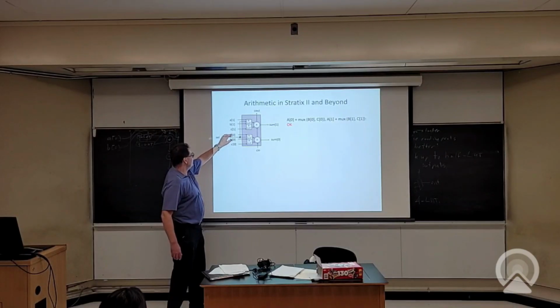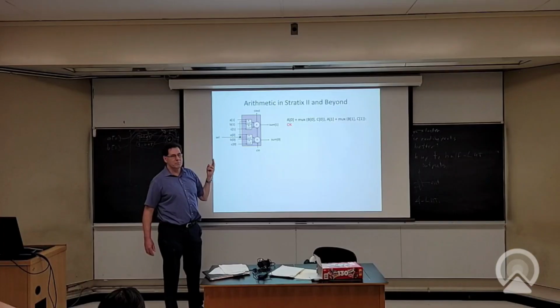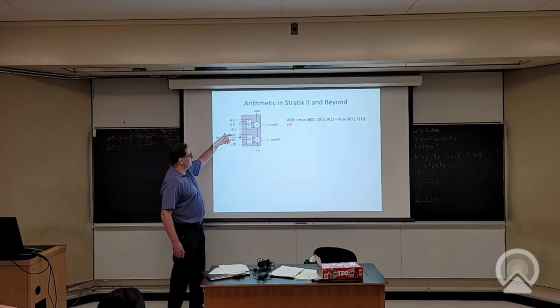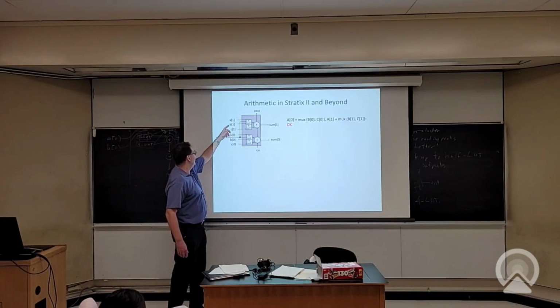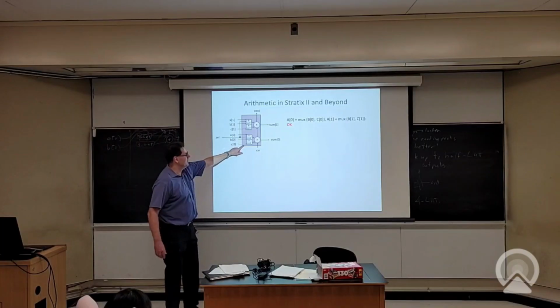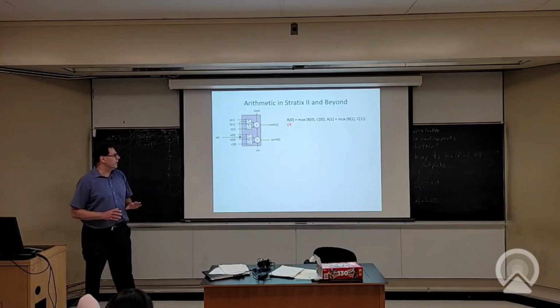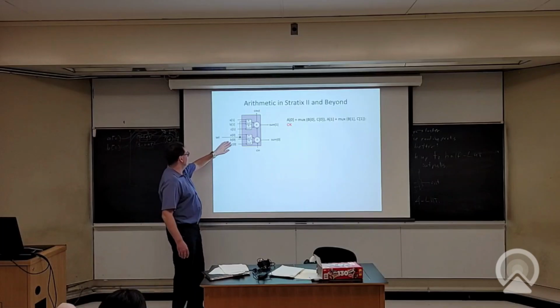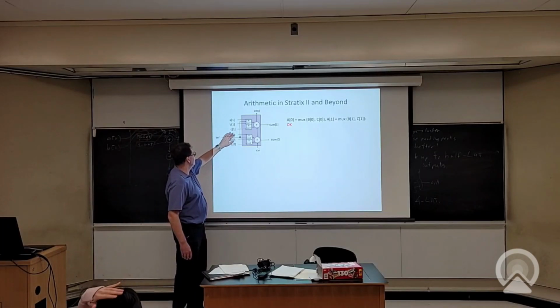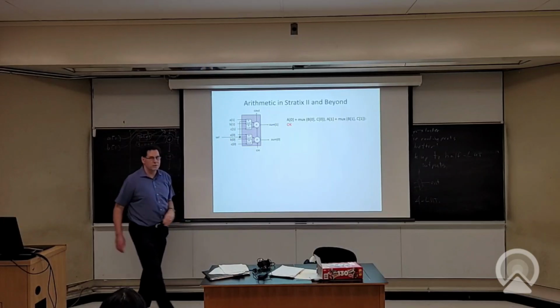So yeah, I've got a mux function, which a 2-to-1 mux just needs 3 inputs, right? So here it should have been B and C, but it's A and B, and I've got a select signal. Same thing up here, and then the other input just passes through. So I don't exceed any LUTs, and if I add up my signal counts, it's 1, 2, 3, 4, 5, 6, 7. So 7 is fine.